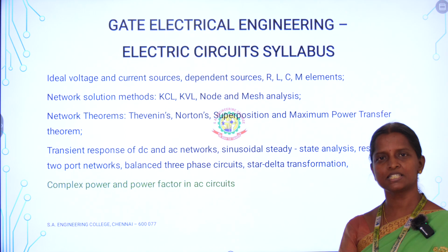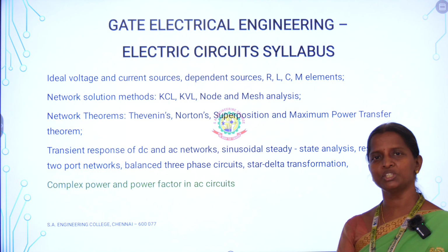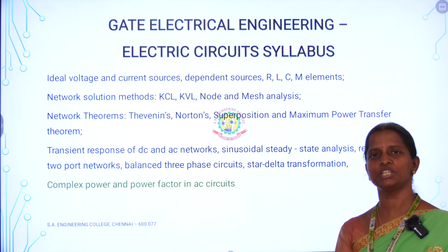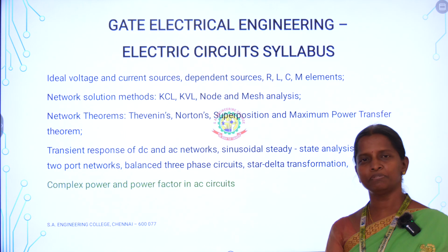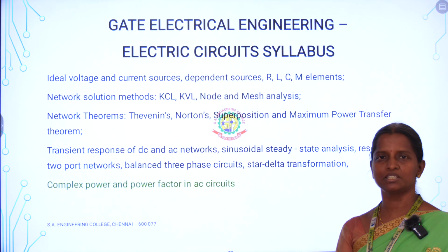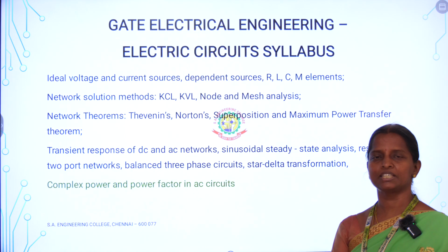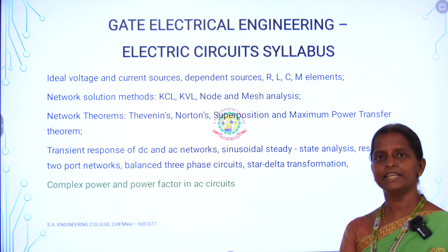Because a resistor dissipates the energy in the form of heat. But the inductor and capacitor store the energy in the form of electric field and magnetic field. So the current may be lagging or leading in nature. That is why we talk about power and power factor. That is not just power, it is complex power and power factor in AC circuits.